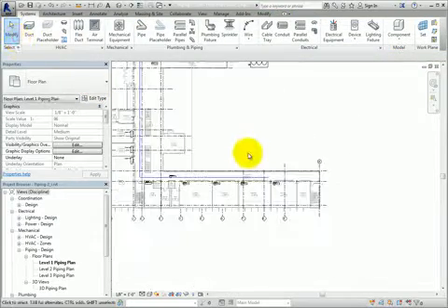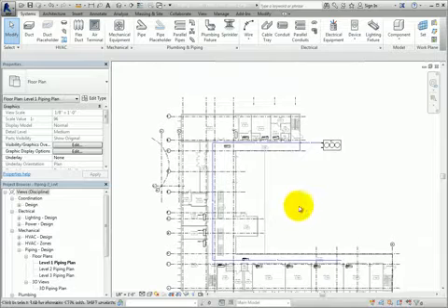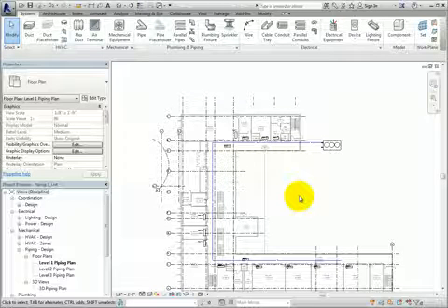As you can see, I used the same pipe diameter to create the entire main supply pipe, and I will size the pipe after the branches are connected. However, you could create several more pipe segments along the path and change the size as you go.